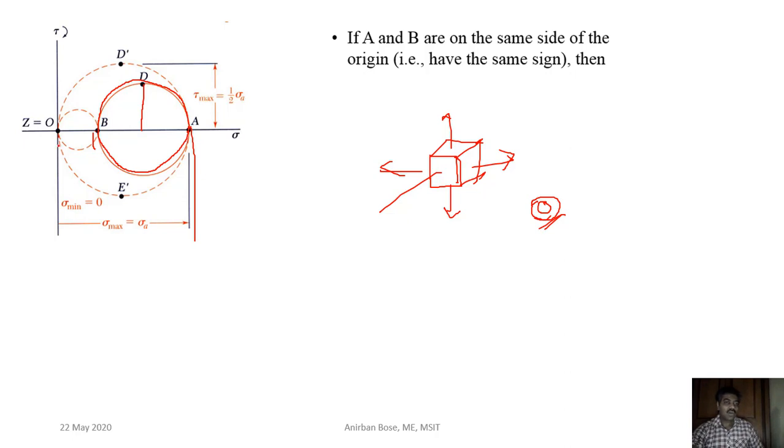Okay, so if you consider with respect to that, then you will get this particular Mohr circle, and there maybe you will get this particular thing. That means the maximum in-plane shear may be this one, but this is not the maximum shear within the whole element, because if you rotate with respect to other principal axis, then you will find maybe out-of-plane shear, where it is maximum.